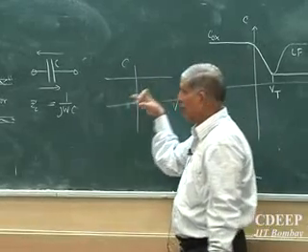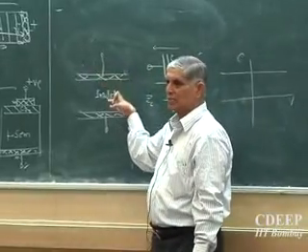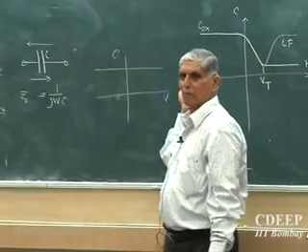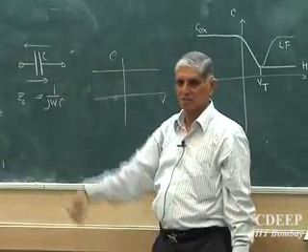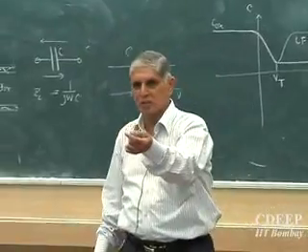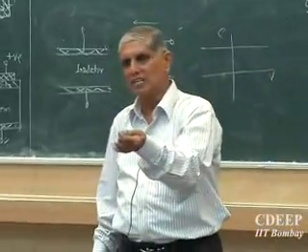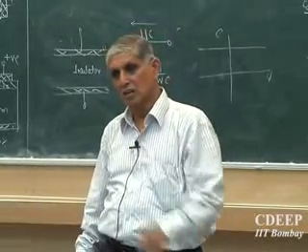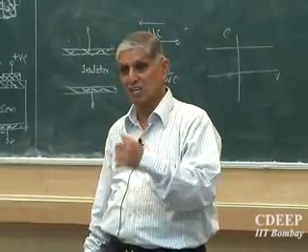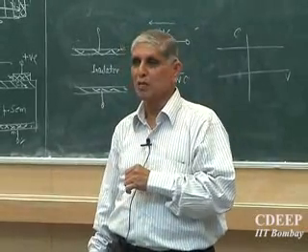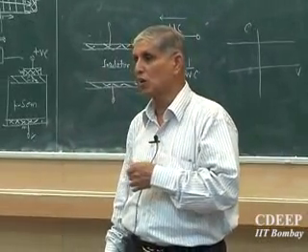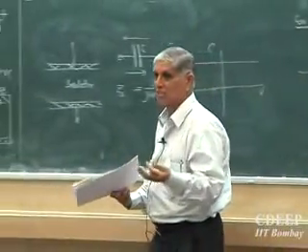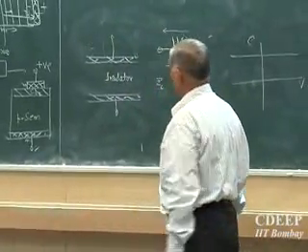Is that clear? If I have a normal capacitor, I see a constant capacitance whether I put plus here or minus here; it's fixed. You put in a ceramic capacitor, you don't look for polarity. Whichever way you put it, it doesn't give any difference. In the MOS capacitor there is a difference, which means some mechanisms must be going on, and this fact is what makes the MOS device very interesting.